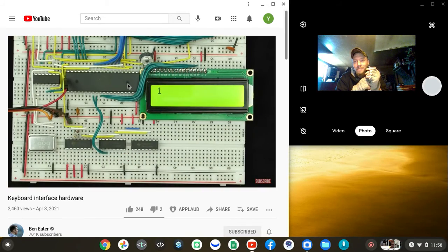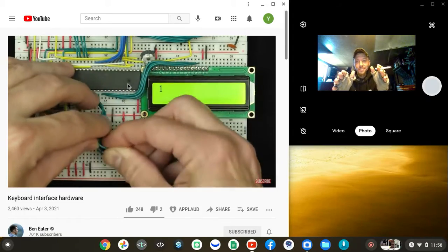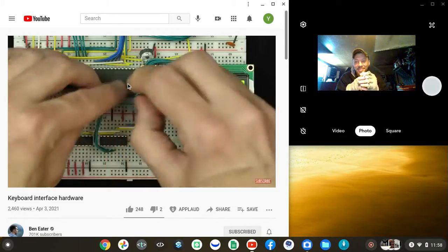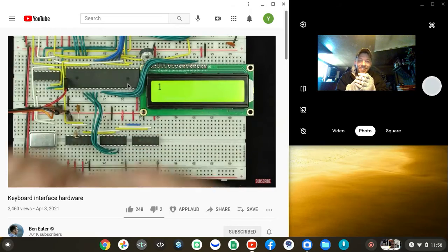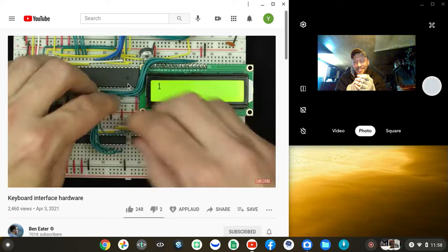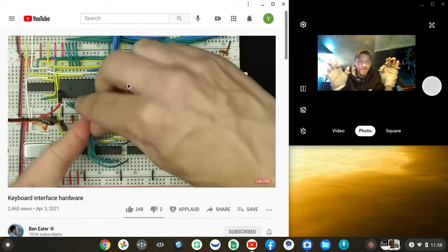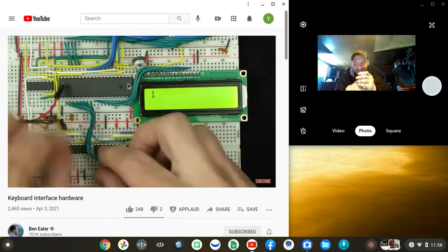And of course, we're getting 11 bits clocked through here, but I'm only going to hook up 8 of them, the actual 8 data bits. So I'm not going to hook up the start bit, the stop bit, and the CRC bit. If I had more inputs here, I could do that, and we could check those as a sort of sanity check. But for now, I'm not going to worry about that. We'll just assume that if we receive a key code, then it's valid.